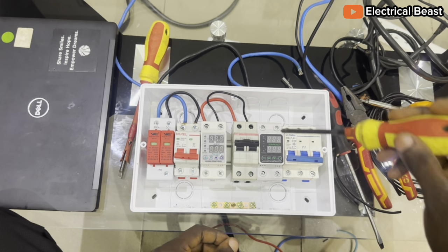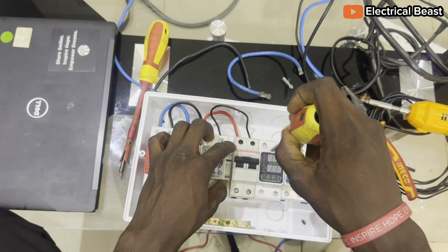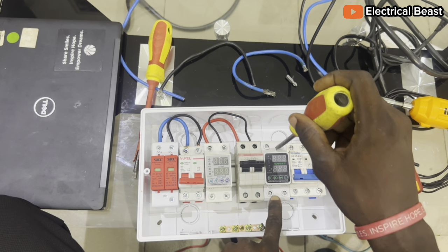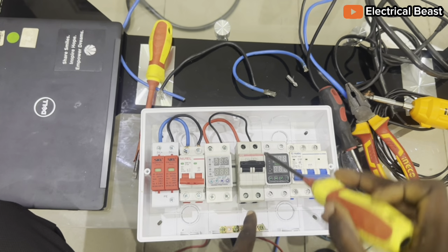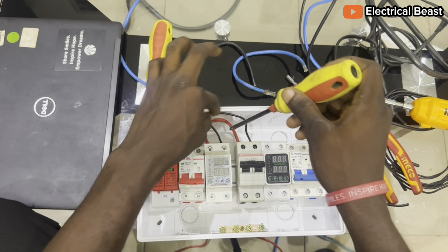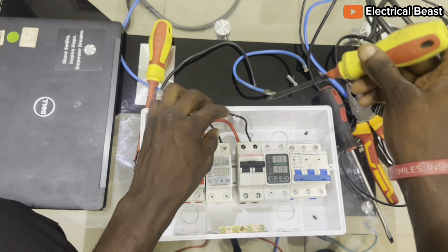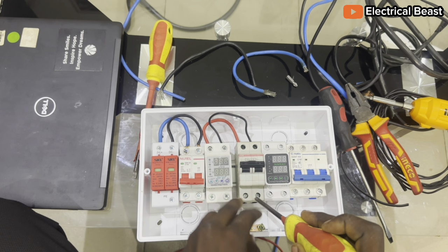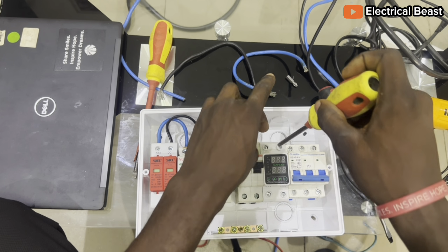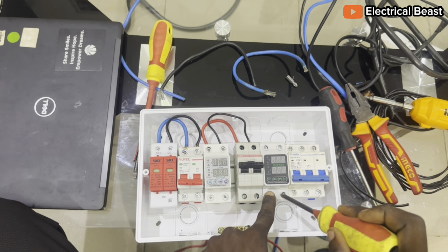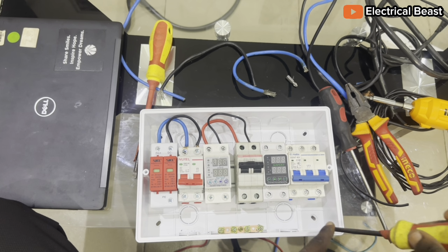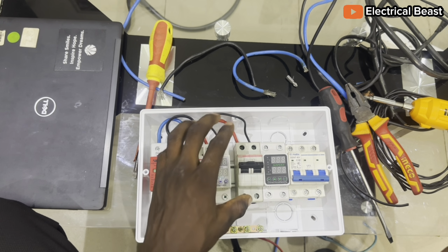How do we connect to this device here? This is the voltage protector. Now, the output of this breaker goes into the input of this voltage protector, or AVS. This is the output of the breaker. You are connecting your grid input to this point while it loops to the surge protective device, the AC surge. Then from this same point, it comes here. When you switch it on, the output comes to this point. So you're going to connect the output from here to the input of this one. Then from the input of this one, you get output here. So when the output comes from here and goes to the inverter's input, that's how the circuit is complete at that point.